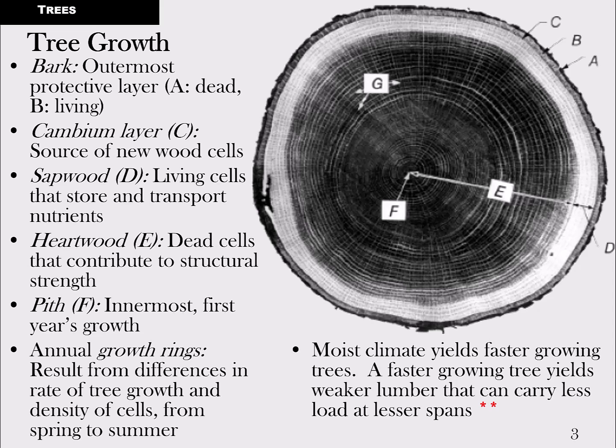And across the grain, across the diameter of that log, on average, you lose about 10% of the diameter. So a 10-inch diameter log becomes a 9-inch diameter log. Doesn't sound like much, but if you're talking about a 10-foot tall wall of logs in your log cabin, well, it's going to be a 9-foot tall wall after a while.